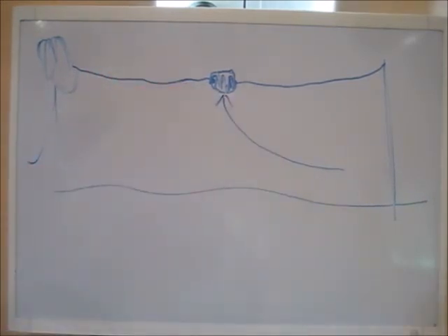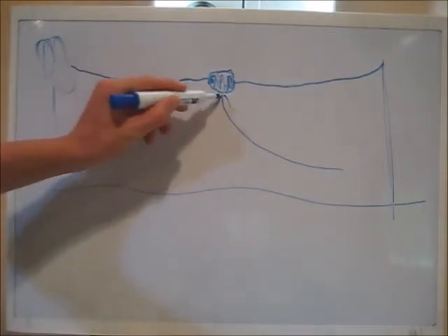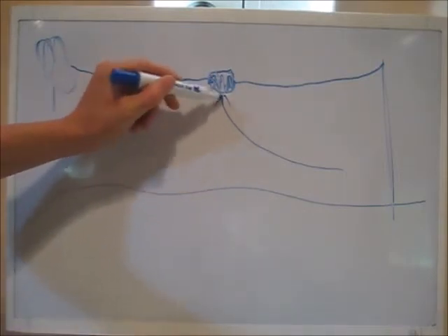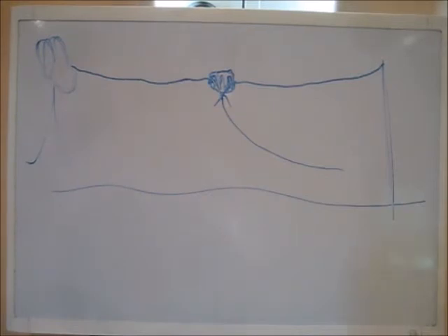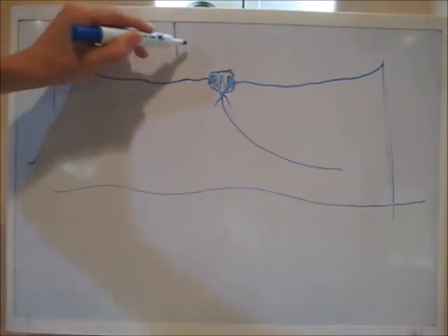Now, coax, if you don't know, has two components to it. It actually technically has four, but two conductive components. The one is the center conductor, and the one is the outer shield. So the outer shield gets stripped back and goes to one side, and the center conductor goes to the other. That makes a dipole.